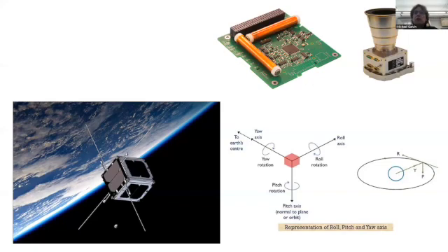And those are also sensory readouts that go into your Kalman filter, because you can integrate your angular acceleration or your angular velocity to yield your angular slew: how much have you turned, what direction are you pointing now. All those gyroscope inputs can be combined in your Kalman filter to really help you know exactly what your orientation is and your roll rate and things like that.